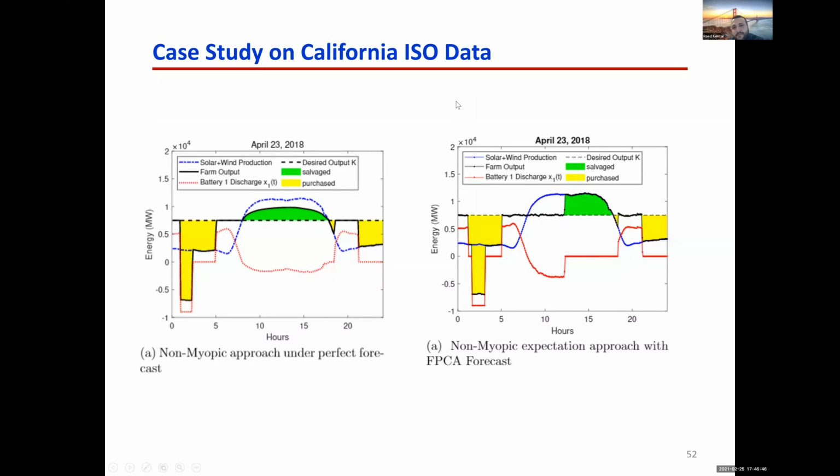If you are not predicting the future or using these sensors to see how much demand is in the future, your decisions are simple. If your demand is more than your supply, just purchase energy, and vice versa, just store. However, if you can predict the future supply of energy, perhaps at some times of the day when the energy is very cheap, you say, let me charge the battery at this specific time, and then buy the energy that I need. And then in the later times of the day, at 6 p.m., when the energy is very expensive, I can discharge from the battery. So these are some situations where the Internet of Things and predictive analytics are indeed very important.